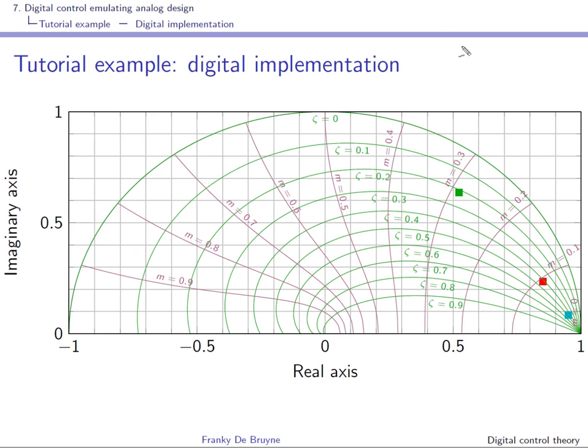We know the process description P(z), and we have the controller. So what we can compute are the poles in closed loop for Ts equal to 0.1, 0.3 and 1. If we compute those poles and place them on this diagram, this is what you obtain. And as I said, this is Ts equal to 0.1, Ts equal to 0.3, and this is Ts equal to 1.